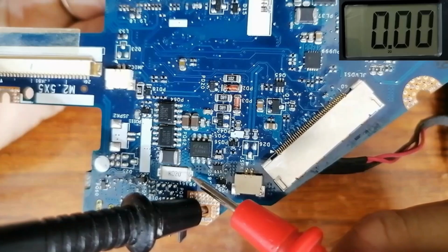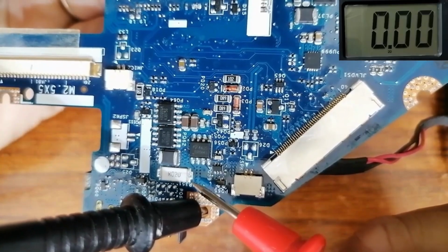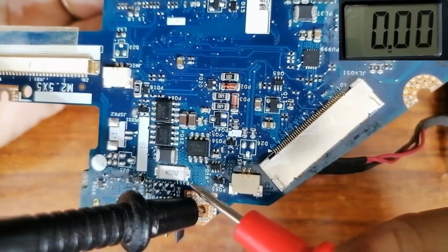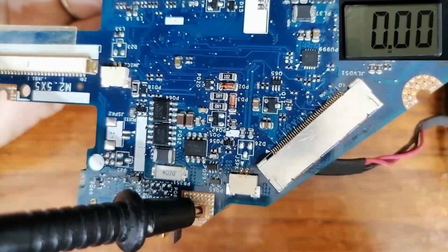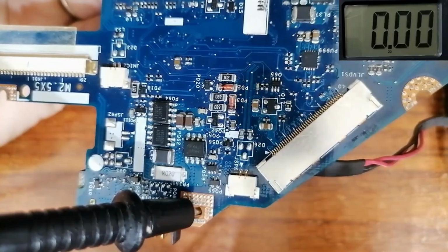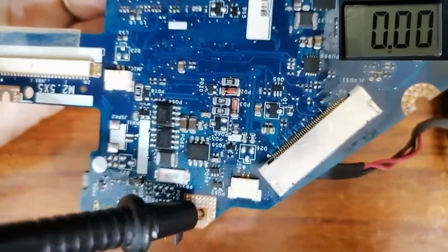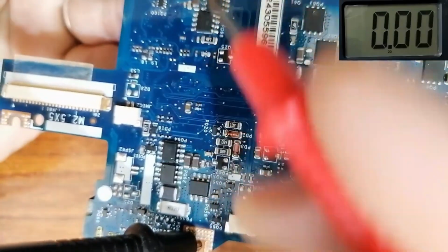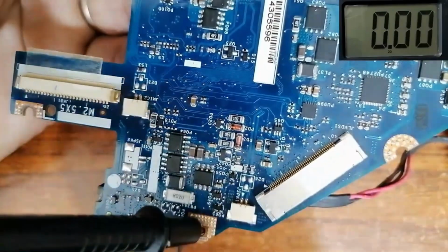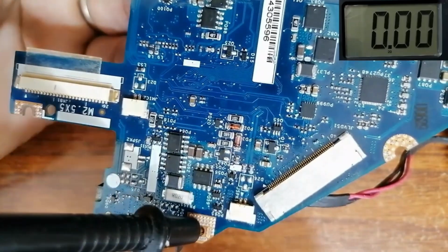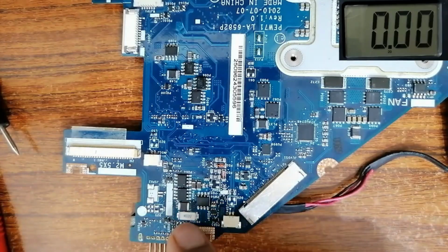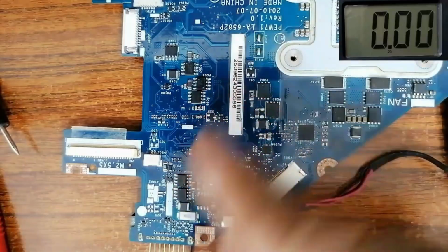So from this point, the 19 volt or the VIN, because it could be 19 volt, it could be 18 volt, 15 volt, 12 volt, 9 volt, depending on the type of the motherboard or the laptop. From this point, the VIN will be distributed to all circuits in the motherboard. I will prove it for you right now and then continue tracking voltage. So to prove to you why the voltage will be distributed from this point to all circuits in the motherboard,